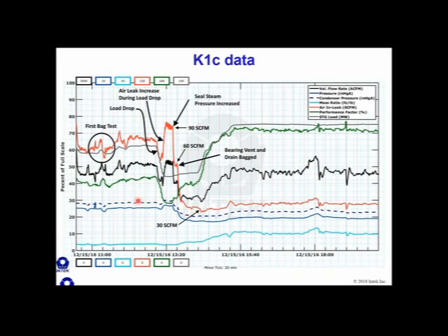So let's go back and take a look at the data. The water to air mass ratio value here on a scale of 10 is less than 1, less than 0.5 here during this high air in-leakage period. We found the leak. I'll show you where the leak was. We repaired one leak and then repaired another leak.